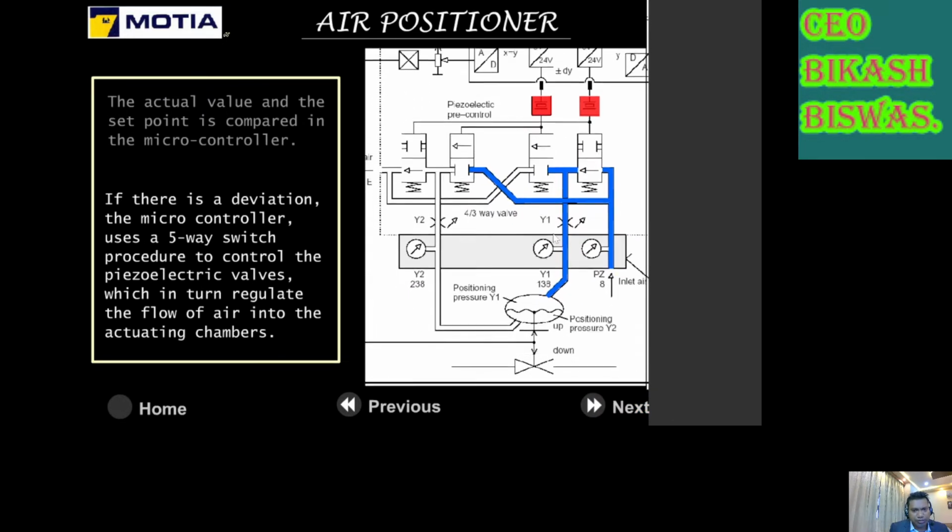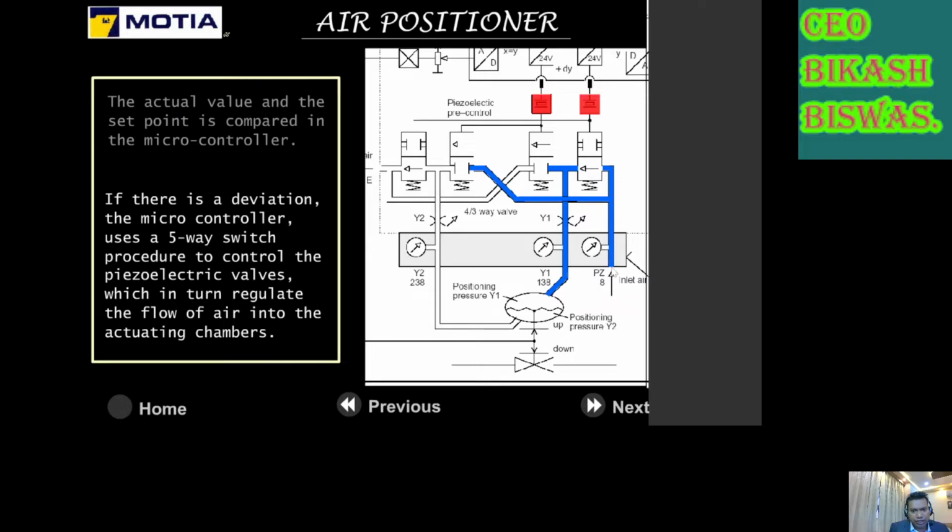You can see, input air pressure is coming from here, and this port is open now, this is coming here, and consequently this is coming here. It is acting on the diaphragm, suppose of the piston of the actuator, acting on top of the piston. So this piston will be shifted downward.